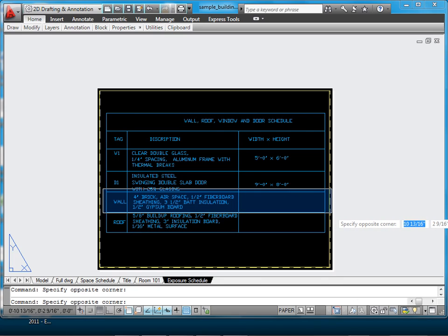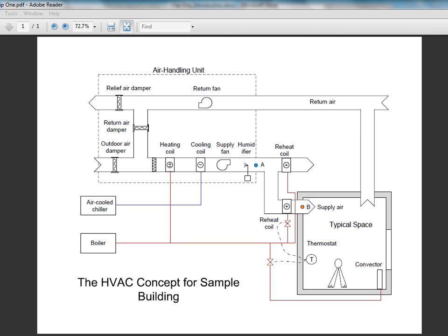Let's study the room geometry. But first, use the drawing compass shown in the title to learn orientation of the building elevations. The legend shows that the elevations facing left side of the drawing face north. Accordingly, the assembling room with the ID 101 has 4 north-facing windows, 3 east-facing windows. The exterior perimeter of the room includes 44 feet of northern wall and 39 feet of eastern wall. Similar measurements have to be done for all other spaces.